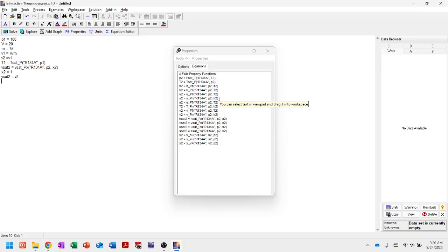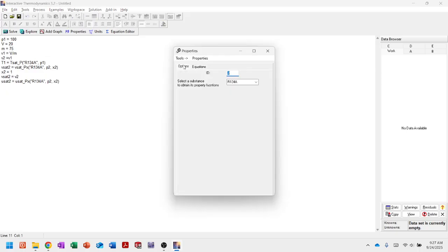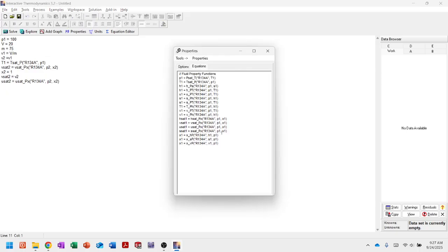And then last, the heat transfer. How do we find the heat transfer? Well, we need to find our mass times our change in specific energy. So U2, I can probably just leave that. U2 is USAT2 at that condition. So I'll grab that. And U1, if I go back to that,